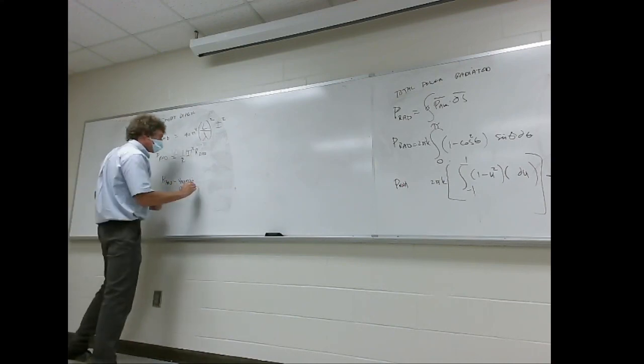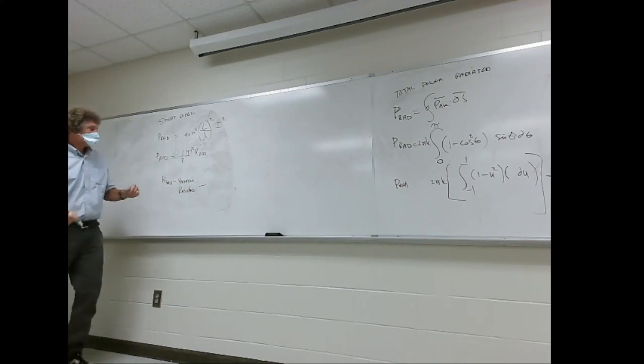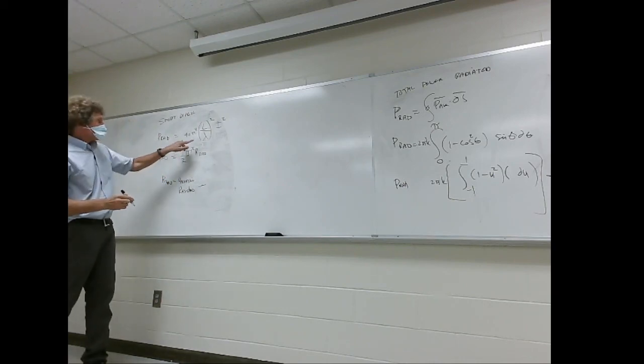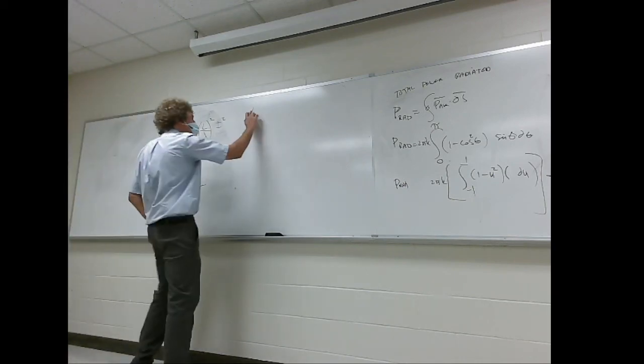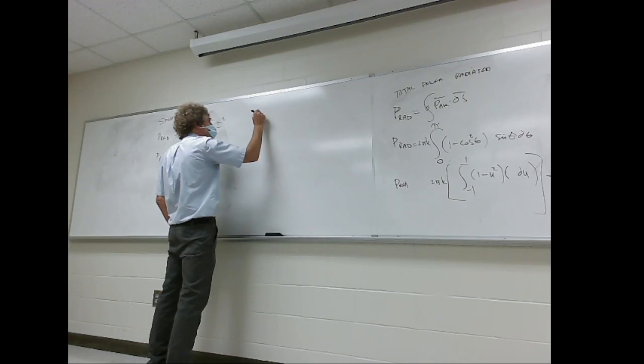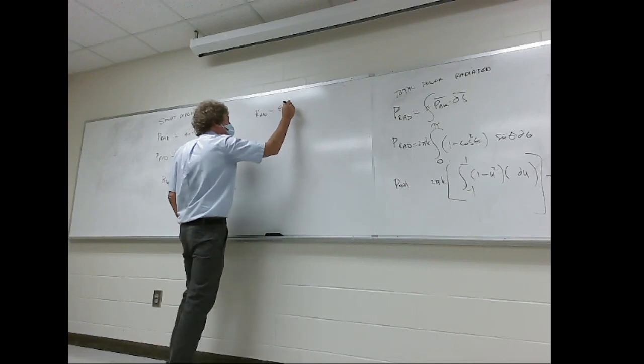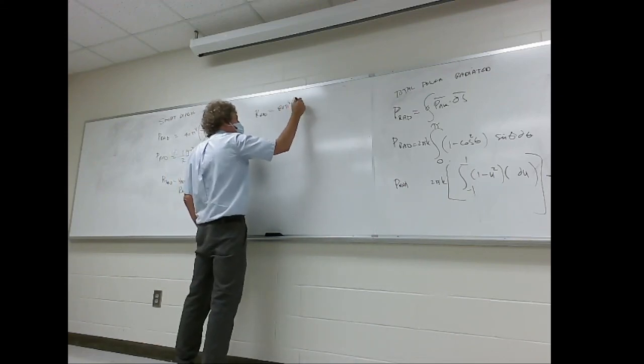And it's in ohms. Now what is our radiation? You'll notice this is just 1/2 right here. Our radiation would be double this. So now we say that the radiation resistance for a short dipole is simply 80 pi squared, and it's the length of that antenna divided by lambda squared.